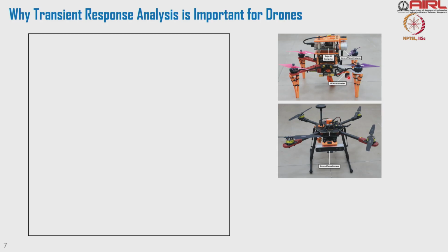But if you look at the LiDAR altimeter, it's going to give them very critical information: what is my height at that particular point? And in addition, we talked about internal sensors, which is very important for controller design, right? Inertial measurement unit, global positioning system. The inertial measurement unit will have both accelerometer and gyro. Together it will give me the attitude, rate, velocity and position information. That's very important for us when we are designing a controller, right?